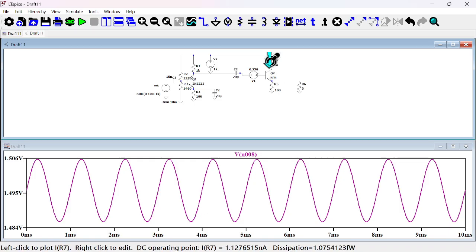Okay, so in troubleshooting, we realize that the voltage here is 11.1111. That's because the transistor is not in forward active mode, as the base-emitter voltage is way less than required.